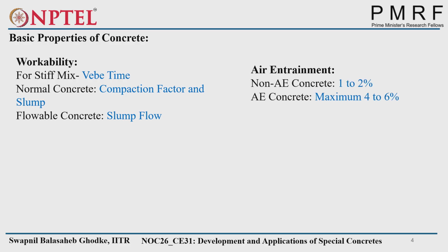In the digitization of concrete nowadays, for 3D printing concrete, people are using the flow table test, which is easier and more appropriate for 3D printable concrete, which is not exactly stiff and not exactly flowable concrete. So according to their behavior, we use different types of equipment.